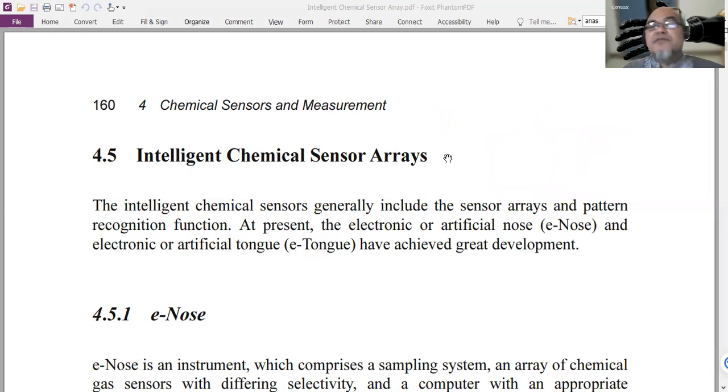So an electronic nose can offer a low-cost alternative sensor to detect and recognize the patterns of gases coming from the breath. And you do not need to rebuild it from scratch every time, like with a selective gas sensor. With a gas sensor, if you want to detect NO only, you optimize the tin oxide sensor so that it has high sensitivity only towards NO and low sensitivity towards other gases. It is still okay when the gases are usually atmospheric gases, like NO, CO, SO2, CO2, oxygen, etc. The problem arises when you want to detect, as I mentioned, the human metabolic gases. It contains maybe thousands of species of volatile organic compounds. How can we design a specific sensor for each chemical or gas species? It is just not economical, not feasible.